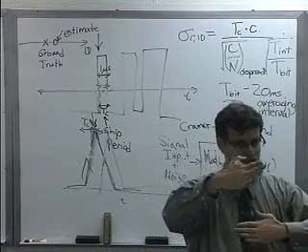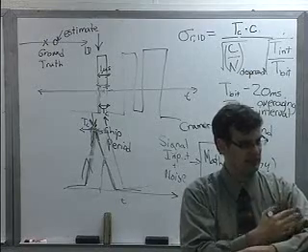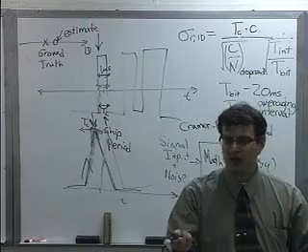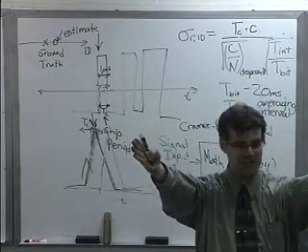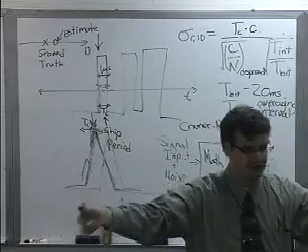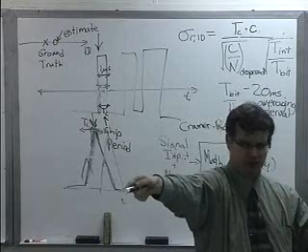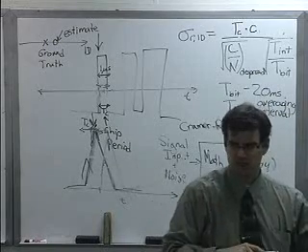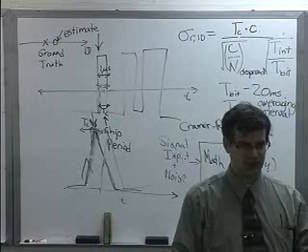Therefore, it should wash across my antenna array with certain phasings. And assuming that a priori structure and a very clean measurement, I will be able to pinpoint beyond the resolution of my spatial array that this signal is coming from precisely this direction on the horizon, 63.059 degrees. And it turns out that those are wonderful techniques until you get noise in multipath.